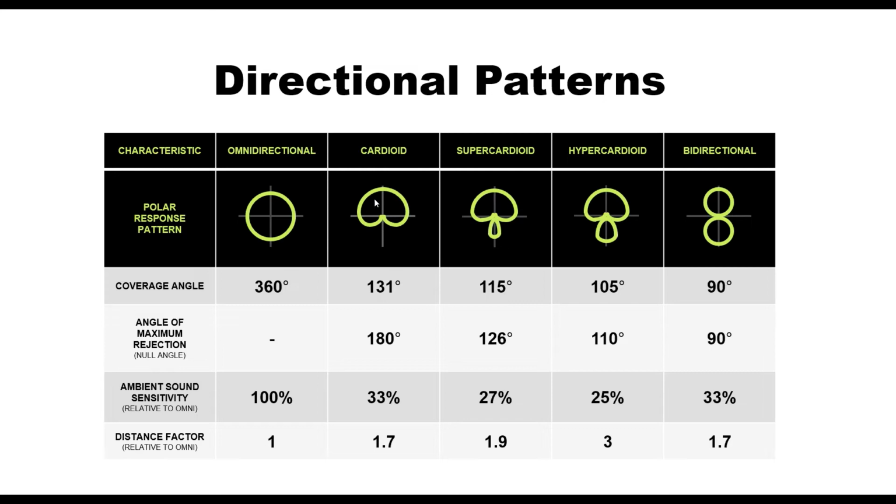But I will say, again, the distance between the microphone and the talker's mouth is still more important or more successful than just going to a cardioid pattern microphone. And where you see this most often is with headset microphones. A lot of the earset microphones that you see presenters use, which is, again, the skinny wire that just sort of hooks over one ear and kind of comes down your cheek there.